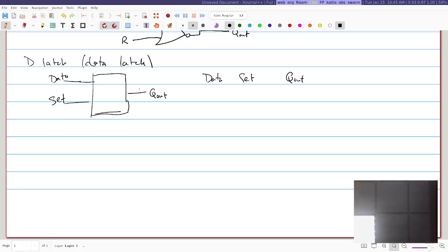And you can imagine this is more useful because, how are we going to use this? Maybe our ALU has some value coming out of it, right? It just computed some value. And that's going to get sent to the memory. And then maybe there's something where we decide, do I want to store that value right now or not? And then we would set something to 1, meaning, yeah, let that value in, store it in the memory, remember it. Or if it's not 1, then it just means, yeah, it was computing a value, but we don't care about it. Just forget it. Because the ALU is always computing values all the time. You can't stop it from computing values.